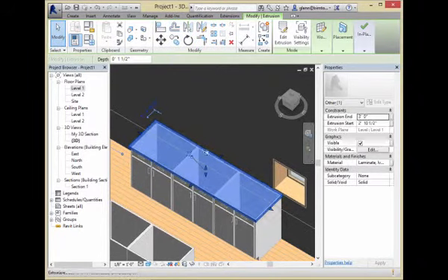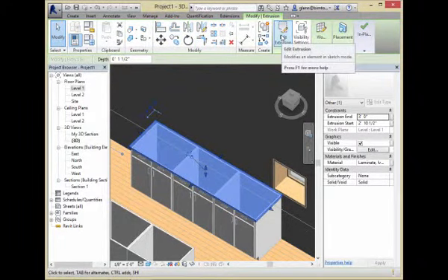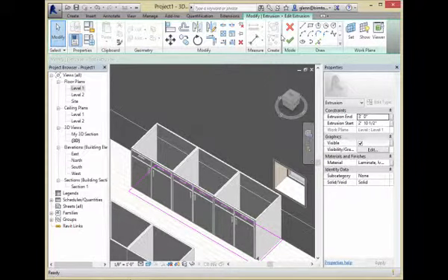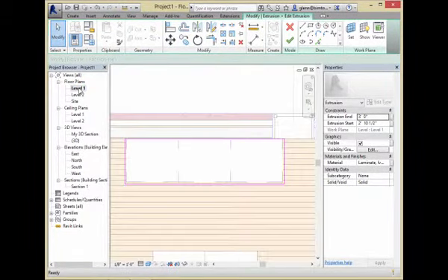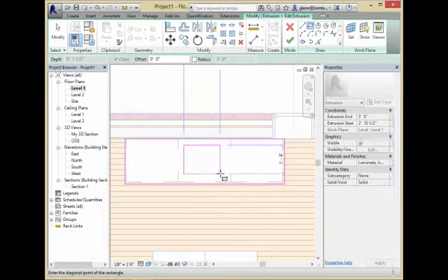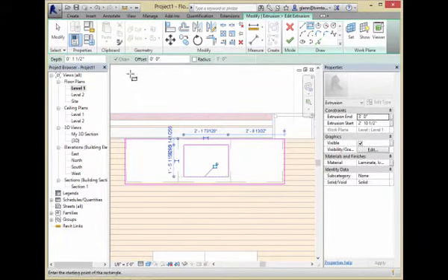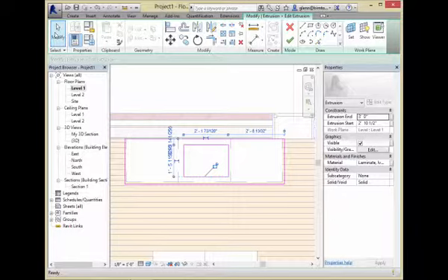I can choose that thing, and it's an extrusion. I can edit it. And now, let me do it in a floor plan. It'll be easier to see. There's the boundary. If I want to put a hole in it, for example, what I can do is put another interior loop. That's a hole in my countertop. If you have a custom size sink that's in a custom location, you can just trace the boundary around that sink and cut a hole in the countertop where you want it to be. And so that's anywhere you want to put holes, just go through and draw an interior loop.